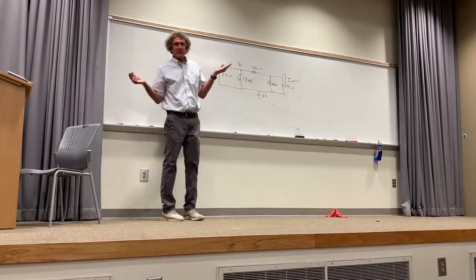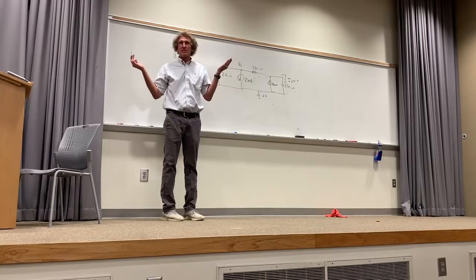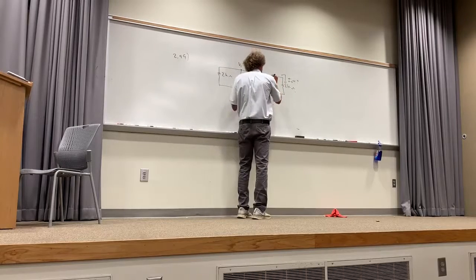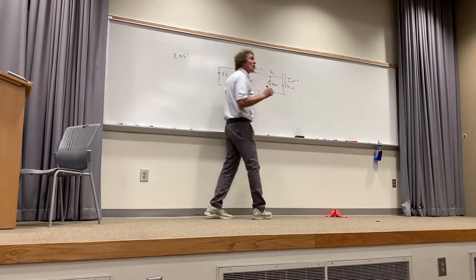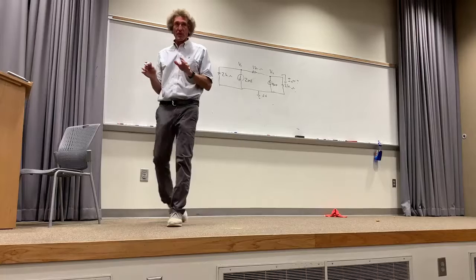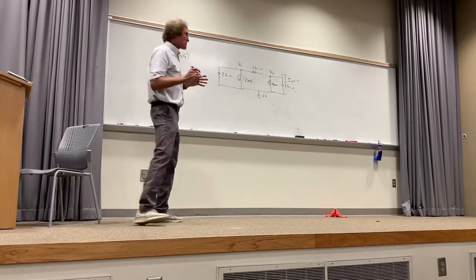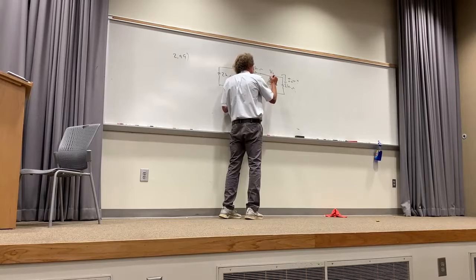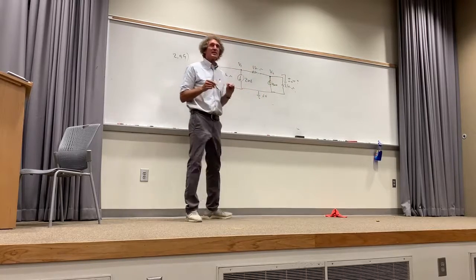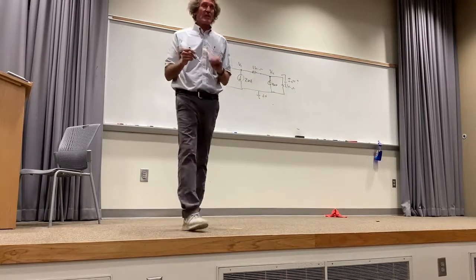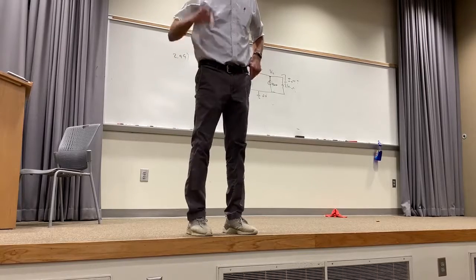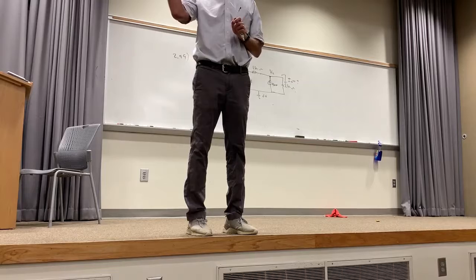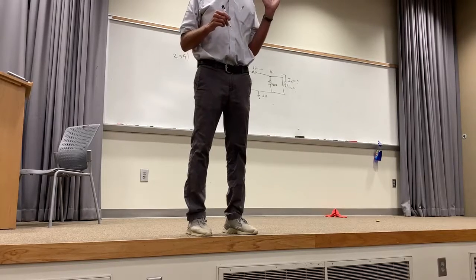I choose a value. V1, VA, whatever you like. There's another point where we don't know the voltage right here, so we can call that V2. You all see that those voltages are not known, right? A node is defined as an equal potential point where there is more than one way for current to get in and out. You all see that that's basically a T right there. You could have a T, you could have 3 things, 4 things, 5 things going in and out of there. Understand? But it's an unknown pressure point, unknown voltage. You all see this, class?